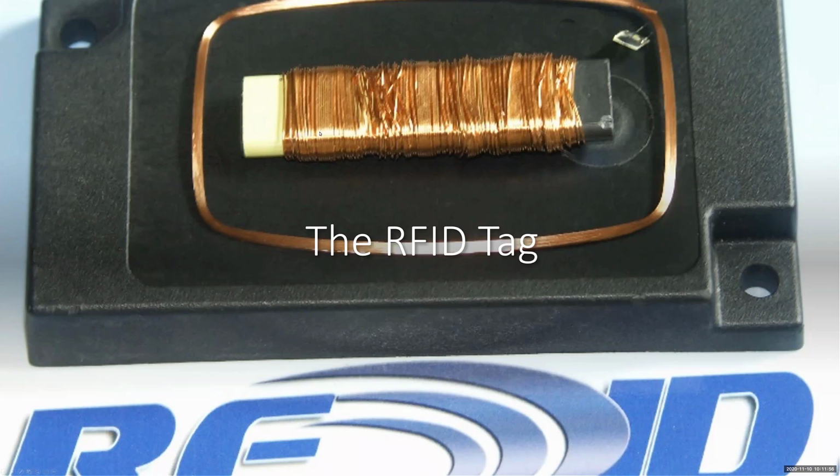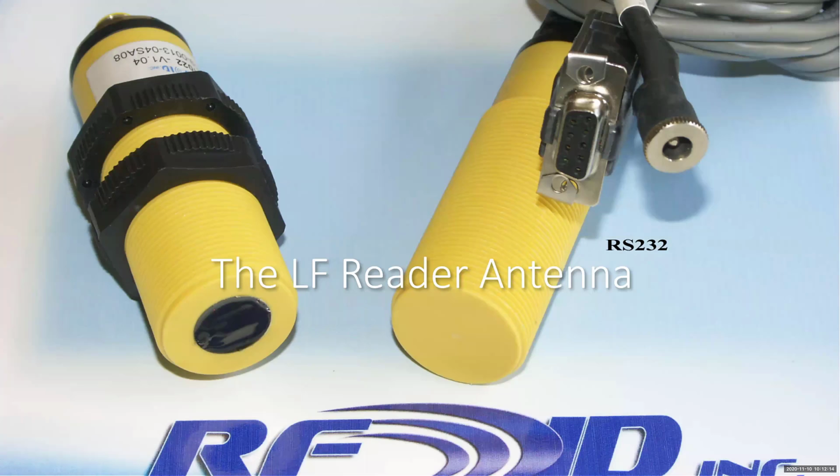So that would give you the ability of having your smart antenna pointing towards the top of the tag rather than the ends of the tag if it were with the ferrite core. In this particular case, the customer utilized the planar antenna. They used the same smart antenna as what we showed earlier with the mannequin application.